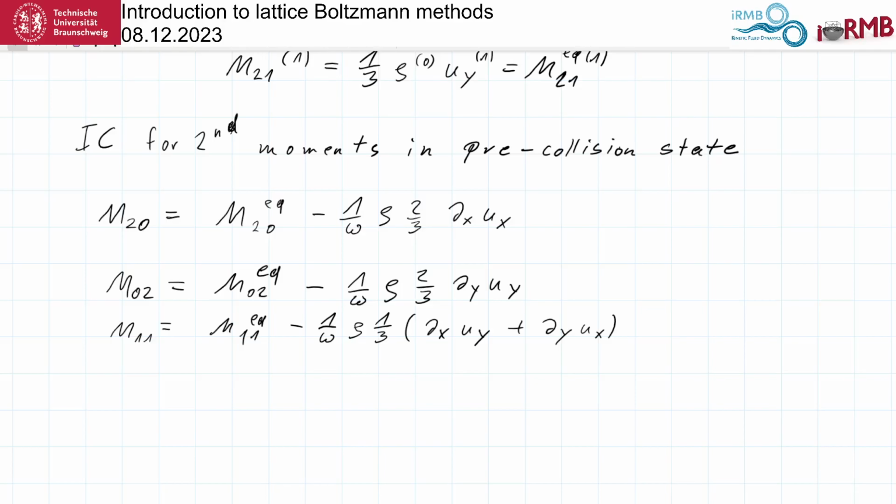There's also other ways of doing consistent initial condition. There is an iterative way of putting initial conditions by solving the Poisson equation, which I'm not discussing here because I've never used this method myself, and I also think it's probably not setting initial conditions. It's more like a preconditioner because you have to do iterations to get to your initial condition. If you do it this way, you can set your initial condition directly, as you would usually put initial conditions. Okay, but there is another method.